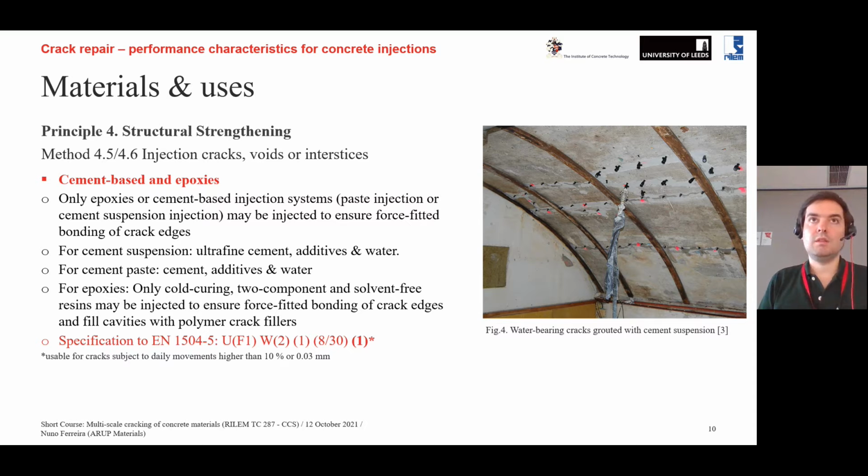The reason being that, one, the E modulus is quite low, so it will never be representative of the material that you want to repair. And second, and perhaps most important, is that epoxies, when they cure, can develop high temperature. And you don't want to get high stress levels. So be careful with the use of epoxies over large volumes.